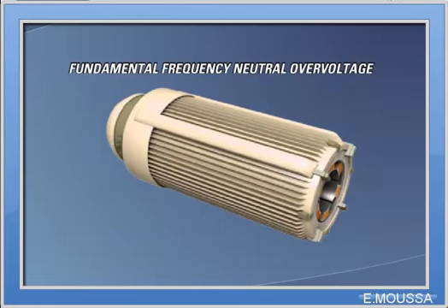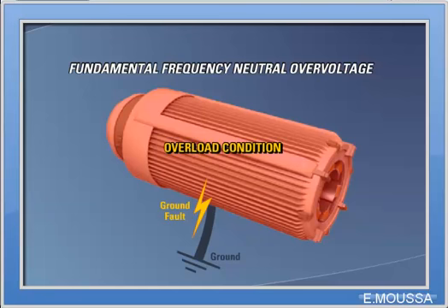Normally, there are two stages of operation, since it is common that the system has been designed to withstand an overvoltage condition for a certain period of time following a ground fault. In such applications, an alarm is generated as soon as the fault is detected. This gives time for the system operators to locate and isolate the fault. The second stage of operation will issue a trip command if the fault condition persists.